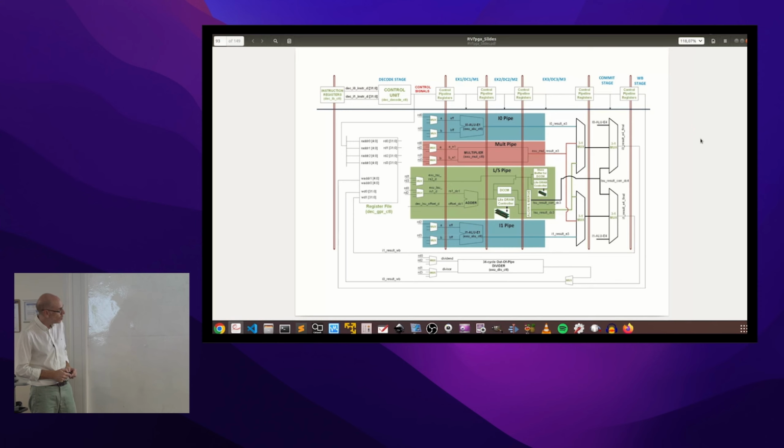Here we only show 2 of them, because the third one is for a specific case that we analyze in a later lab. We'll see later. So we have 4 read ports because we need 4 operands per cycle, because we have 2 instructions executing. And we need 2 write ports because we may have to write back 2 results in the same cycle, right?